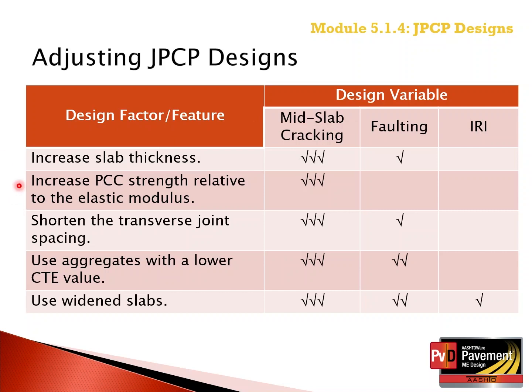So increasing the slab thickness significantly reduces mid-slab cracking and only slightly reduces faulting. It has really no impact on IRI when you exclude its impact already for mid-slab cracking and faulting.